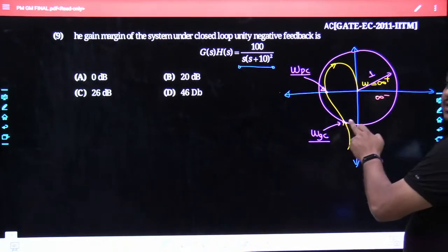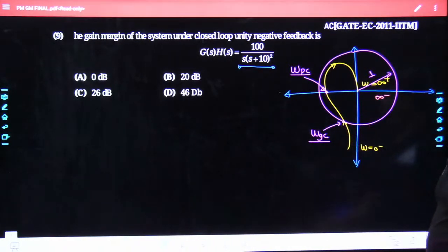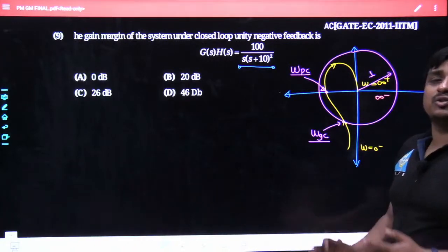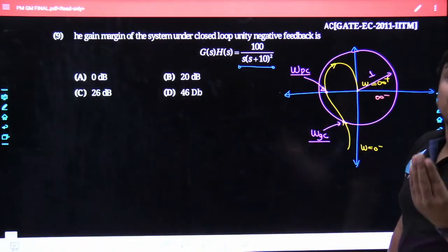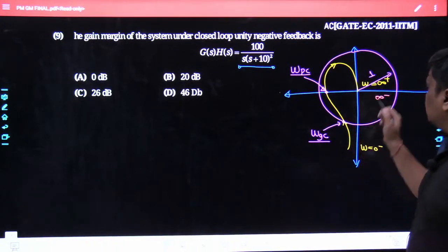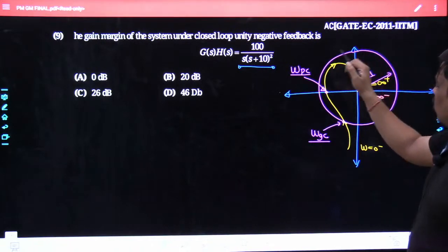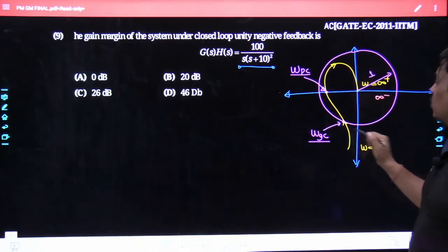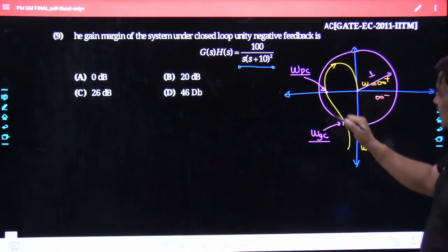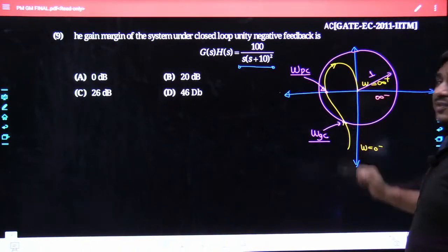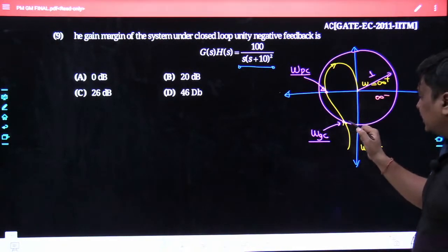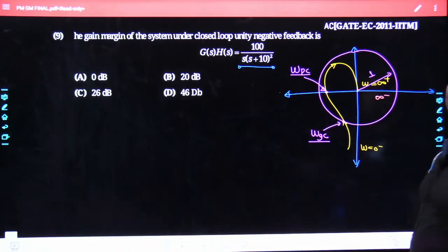Keep in mind, once we talk about the Nyquist or the polar plot, the gain is in linear scale, which is nothing but the unity. The gain over the Nyquist plot or the polar plot is nothing but a constant circle line, and it is crossing the constant circle line with the magnitude of 1 at this point. So here the operating frequency would be omega GC.